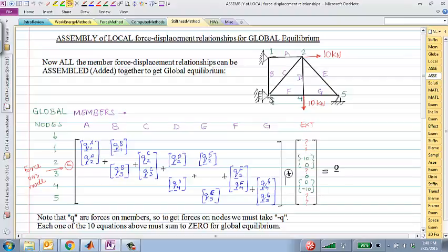Look at node 3. This is a special type of a node. In the x direction, the displacement is fixed, 0, and the reaction is unknown. But in the y direction, the displacement is unknown, but the force in the y direction is known. The force is 0, right? So this will always be the case that at a given node, either displacement or the reaction force would be the unknown. And given 10 equations, I can either solve for the displacement unknowns or the reaction unknowns. And I'll show you how to do that.